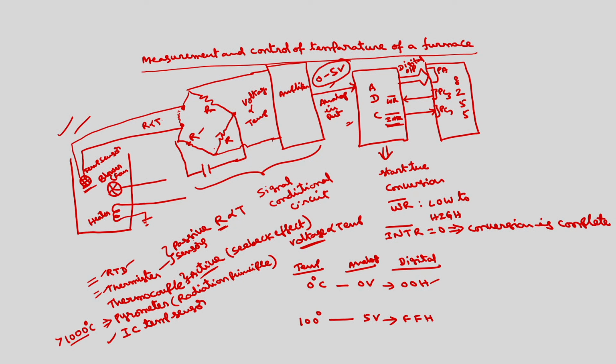Okay. Now if I want to control also, I am using another pin of another port to control this fan and heater. So I will use say PB0 and PB7. This I will connect to the fan. I am not showing that connection, I am just writing. So this point and this point have to be connected. This I am going to connect to the heater. So this point and this point have to be connected.